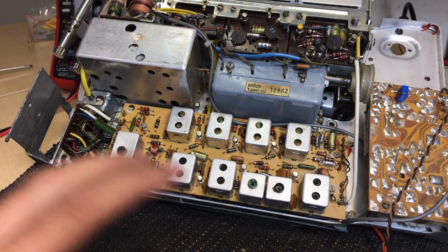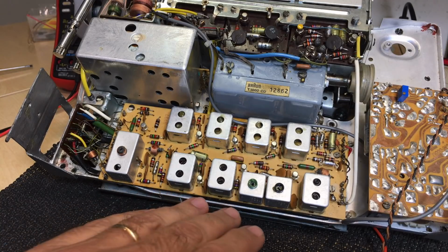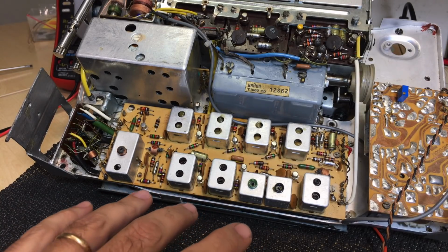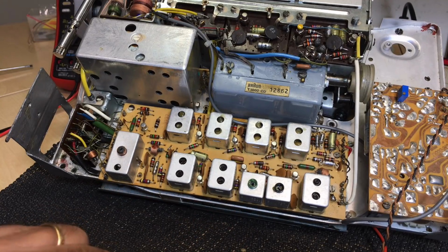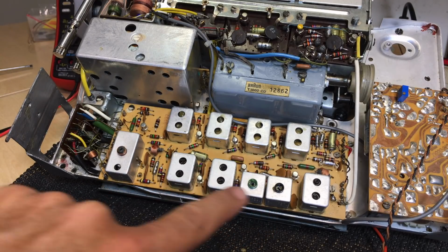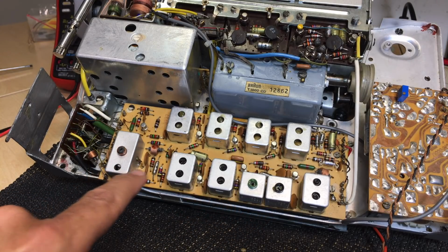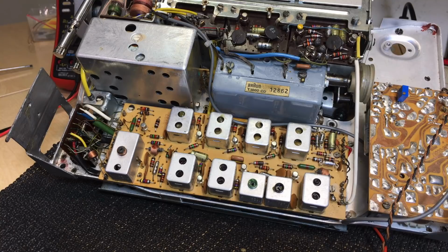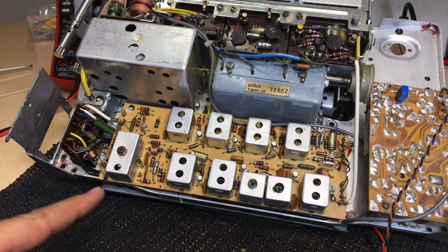It's like dried noodles. Bring your own water, you save on shipping and things like that. What it does is it saves on transmission power because the carrier takes up a lot of power. Now, what it means is when you're putting that signal through here, you need to add the carrier, and the carrier should be at the same frequency as you would normally have in a receiver, which would end up being the IF frequency when it gets to the IF chain over here.